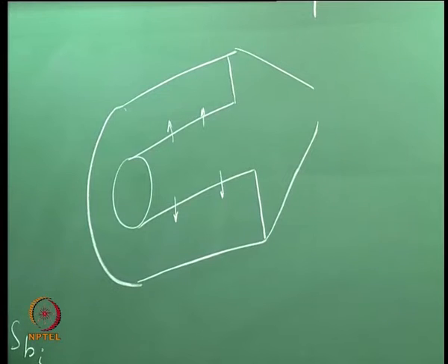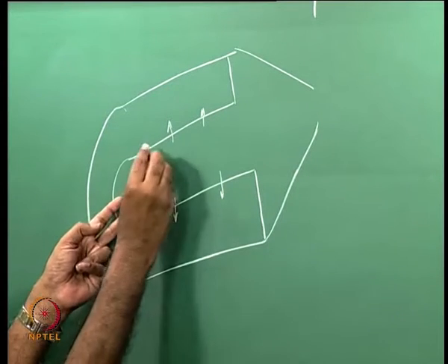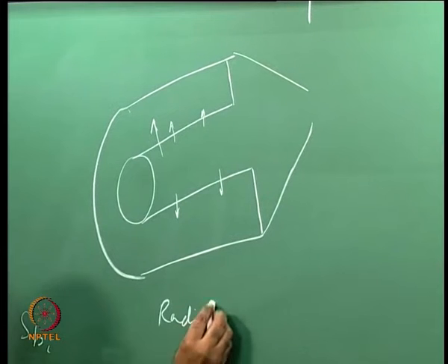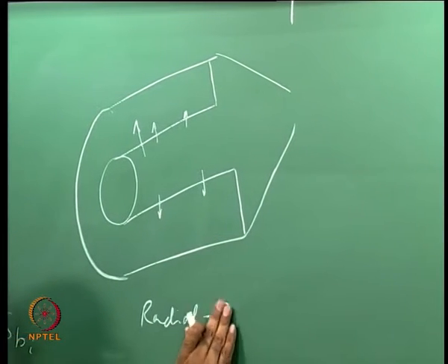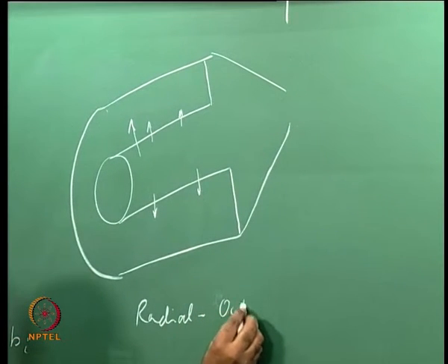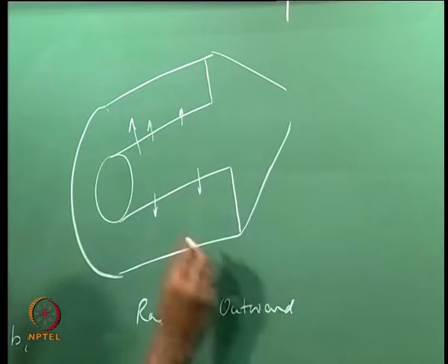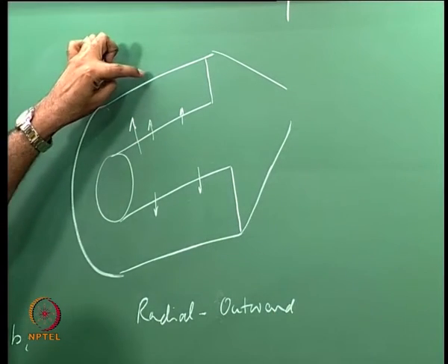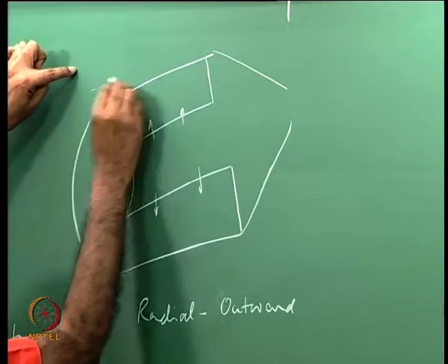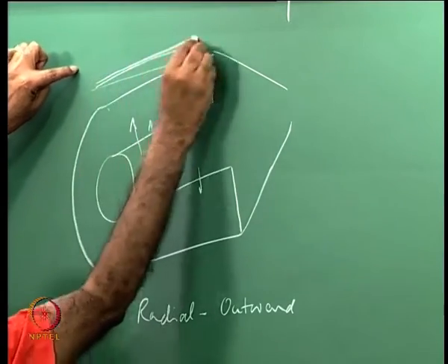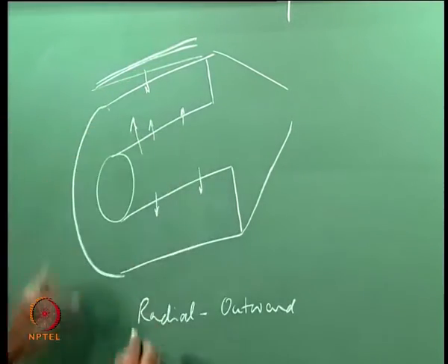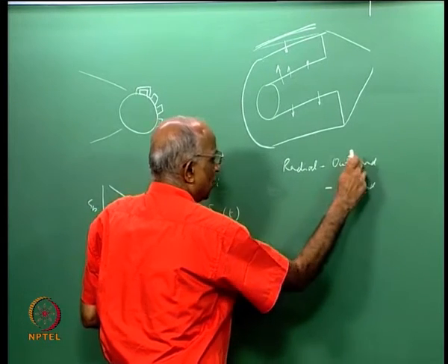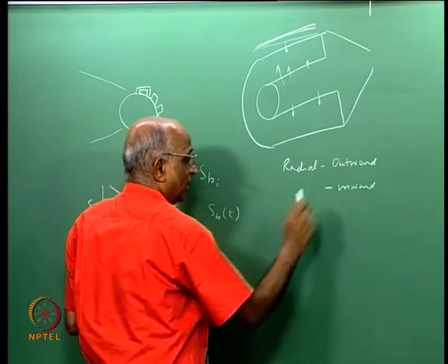and therefore my burning surface area, the burning is radial and it is outward from the center. Burning takes place from the inside surface to the outside. If I ignite it on the outer surface, maybe I have, let us say, a gap and the case is insulated, I allow it to burn inward, therefore I say radial inward. This was progressive, this was regressive.